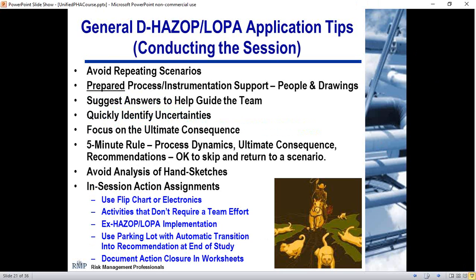All those things are key parts of instrumentation and control and protection systems, part of a modern facility. Your instrumentation engineer needs to be very well prepared with at least a general idea of set points, what the functions of your control and protection measures are, and especially safety instrumented systems, what their recommended pedigree is going in.